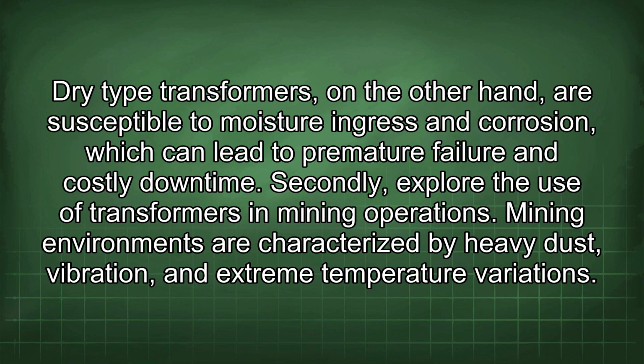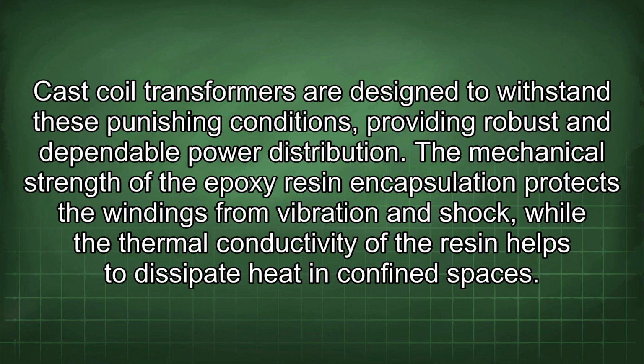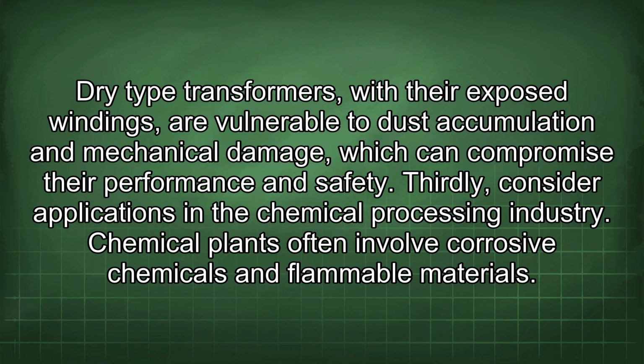Secondly, explore the use of transformers in mining operations. Mining environments are characterized by heavy dust, vibration, and extreme temperature variations. Cast coil transformers are designed to withstand these punishing conditions, providing robust and dependable power distribution. The mechanical strength of the epoxy resin encapsulation protects the windings from vibration and shock, while the thermal conductivity of the resin helps to dissipate heat in confined spaces. Dry-type transformers, with their exposed windings, are vulnerable to dust accumulation and mechanical damage, which can compromise their performance and safety.